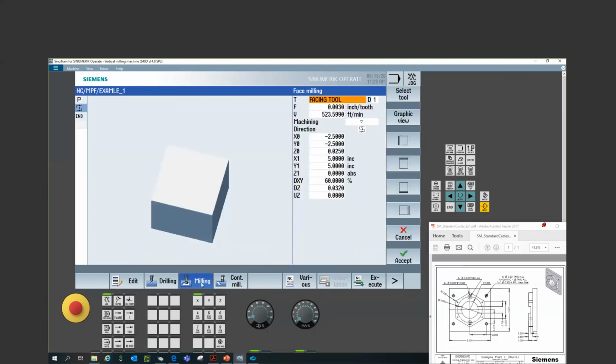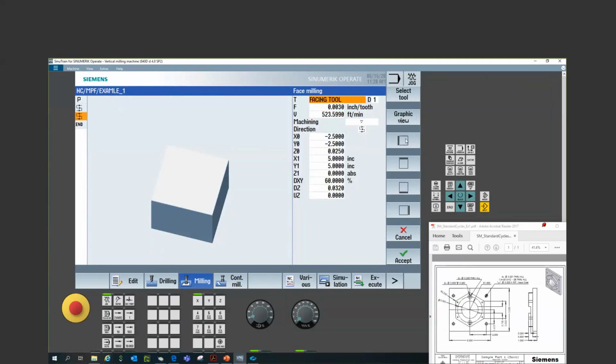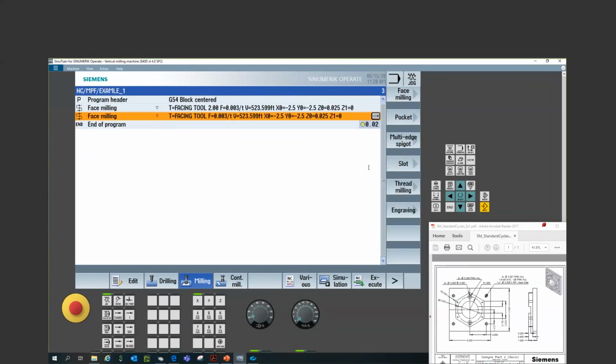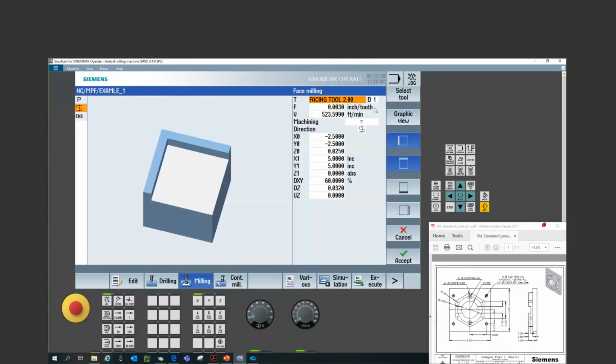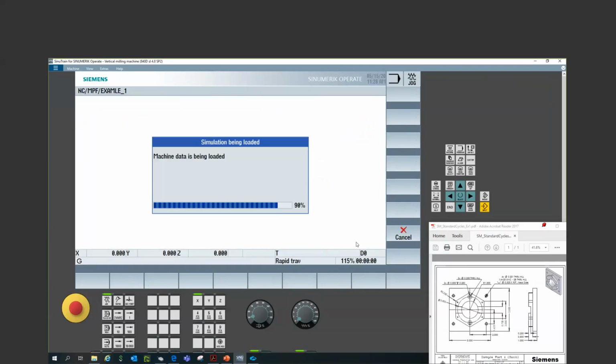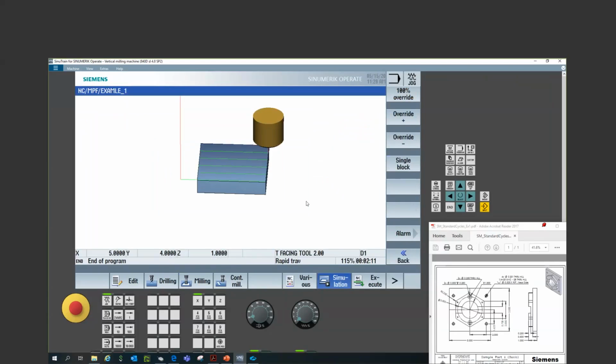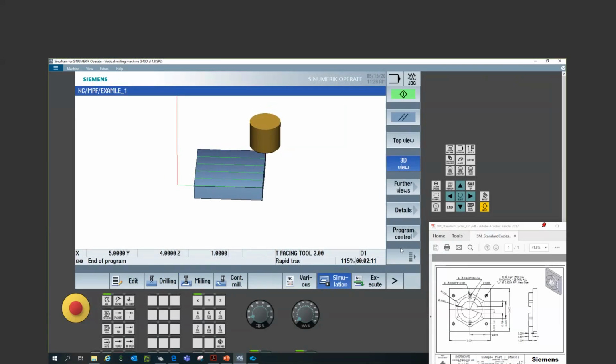to my cycle. Let's see, and then I'm just going to go ahead and turn these modifiers off. Hold on just a minute. Delete. Put an extra cycle in there accidentally. Don't want that. Okay, turn these modifiers off. Accept that. Simulate it. And then there's our part.